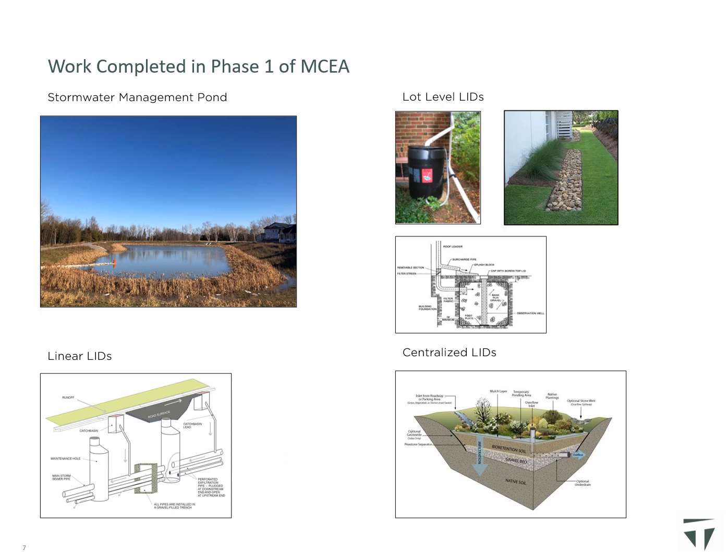Before drainage from the developed areas discharges to an appropriate outlet, it may first drain to a stormwater management facility such as a wet pond or constructed wetland, a dry pond, or a low-impact development measure. Stormwater management facilities are typically designed to limit storm flows from a developed area to pre-development levels and to remove sediment and other pollutants from storm runoff prior to entering the natural drainage system downstream.